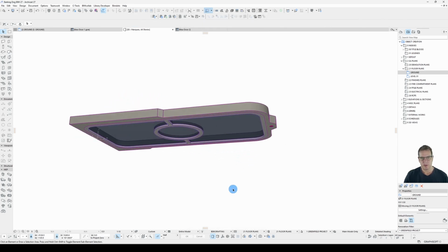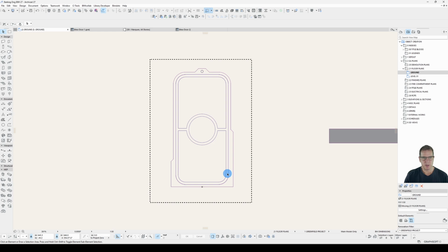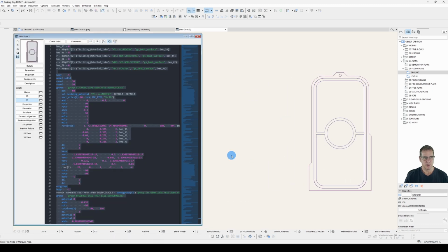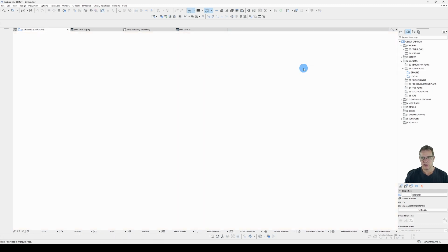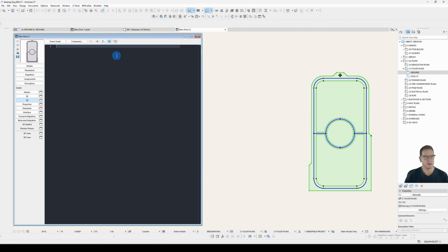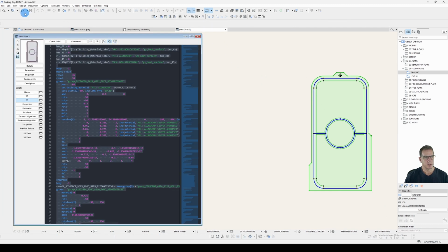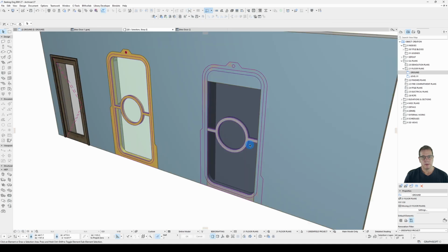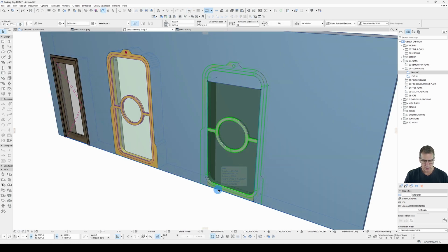So all of my surfaces are overridden in my geometry. Come back to my object, delete the 3D script, select on my floor plan, and generate my script. Save. Now with the create from floor plan method, all of the attributes are locked. I have no control over them.